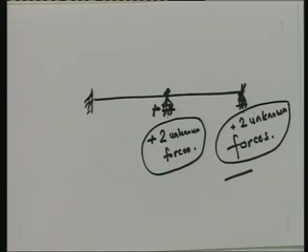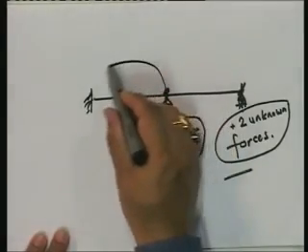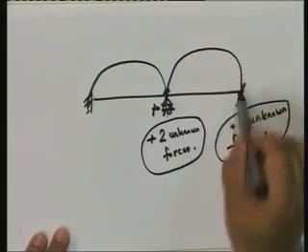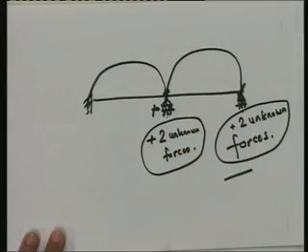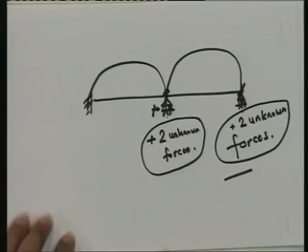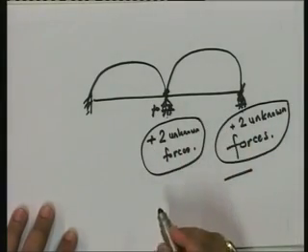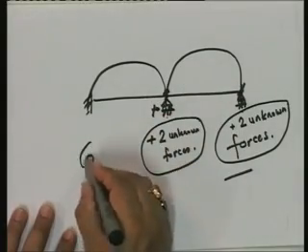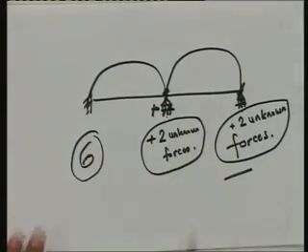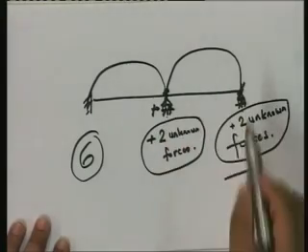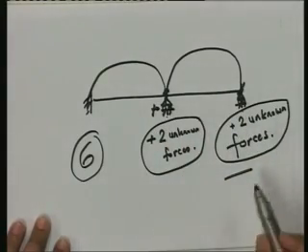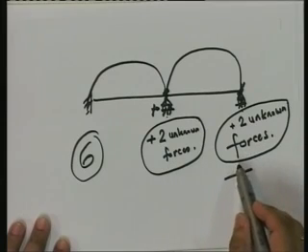So now let's look at this problem. How many rings does it have? Think about it. This is 1 ring. This is a second ring. Independent rings. So, how many degrees of indeterminacy does this fixed structure have? Obviously 2 rings, 6. Think about it. 6. Now, to generate these 2 rings, how many unknown forces did I add? 4. 2 plus 2. 4.